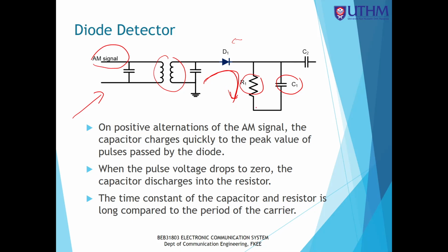During the forward bias, the RC tank circuit will charge to a certain level, and then when the current changes polarity and becomes reverse bias, the RC tank circuit will discharge to produce the other half of the signal. It is a similar concept to the modulation process. And this C2 capacitor will remove the DC voltage, so that the signal will be centered at the axis.